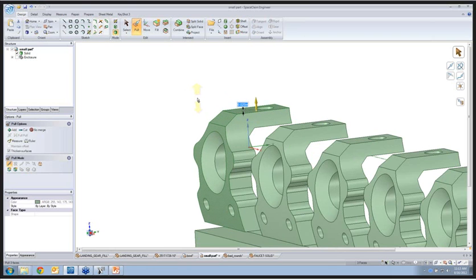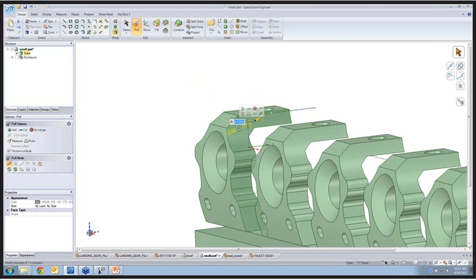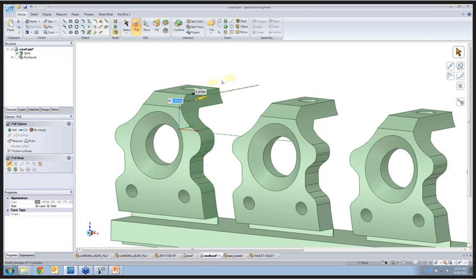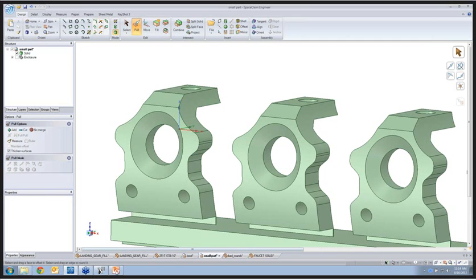I would probably do a copy and paste so that I could preserve the original, and then on the second model I have, I would do an offset of faces, 5, 10 thousandths, whatever stock you want to add to it. A chain of faces that's tangent, I could grab those, pull on those as well, and those are actually offsetting. It looks like they're just moving to the right, but they are in fact doing a normal offset. So adding stock, yeah, definitely you can do that in SpaceClaim. Great use of the tool as well.